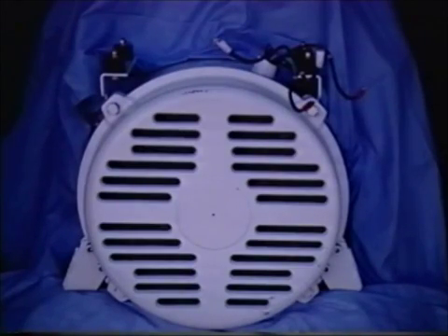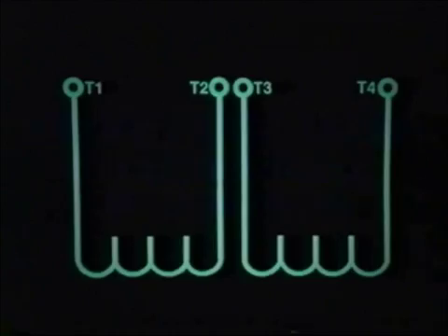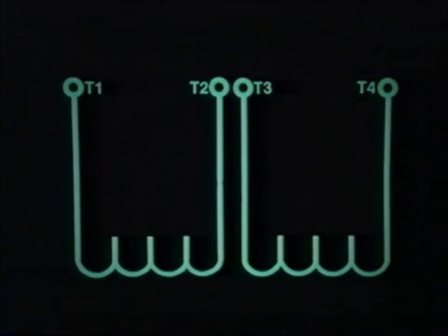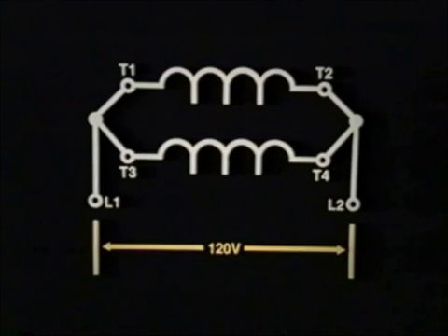We now come to the most commonly produced type of single-phase alternators. These are the single-phase 4-lead reconnectable alternators, which are much more versatile than the 2-lead or 3-lead alternator. The single-phase 4-lead unit has a 2-circuit armature, usually designed as 120-volt coil groups. When connected in parallel, the unit provides 120-volt 2-lead service.